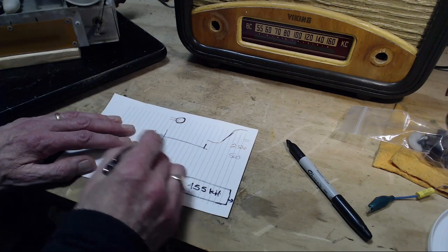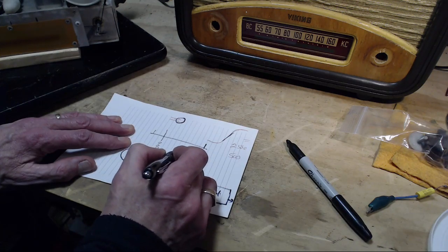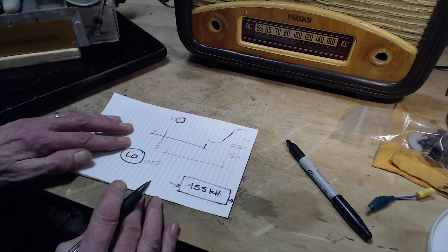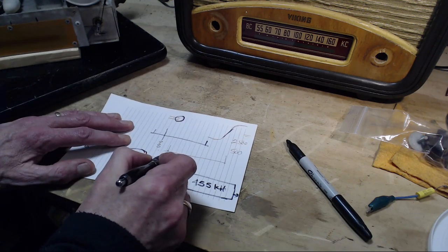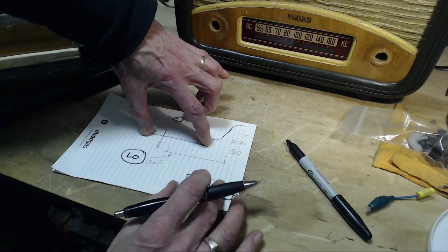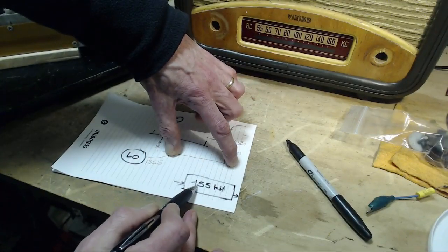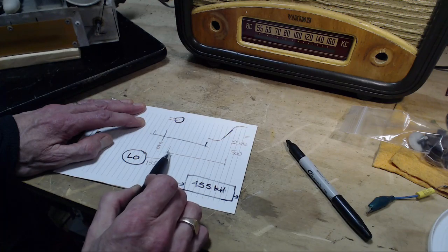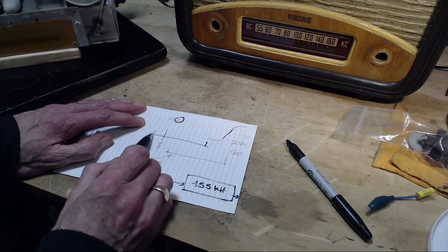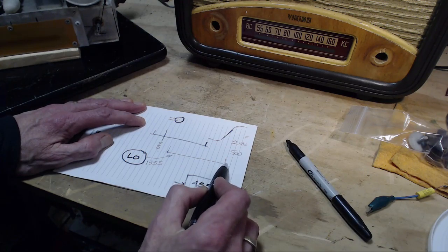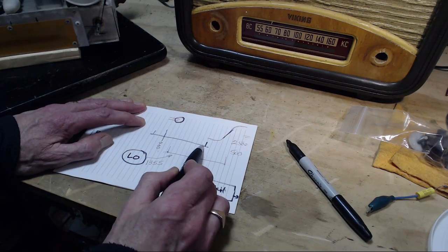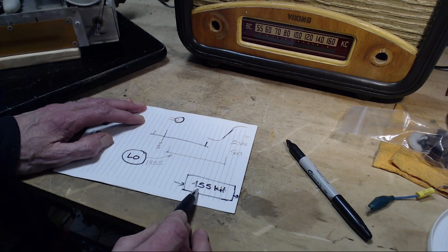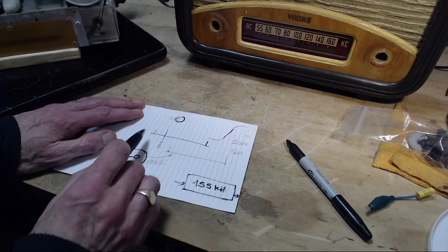So we can draw the chart for the local oscillator. I'm going to draw it something like this, showing the relative frequency range of the local oscillator. If you notice, it's just the AM band pushed higher by 455 kilohertz. So when you have the local oscillator down here, it can mix with a signal here and produce the 455. And up here, it's mixing with signals here and producing 455 again. Always producing 455. Well, won't the local oscillator mix with all the other signals?